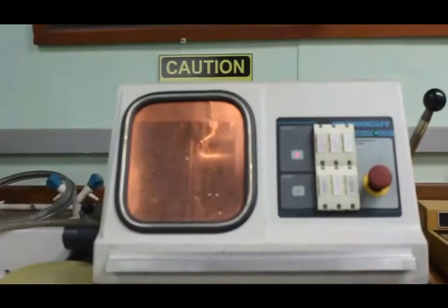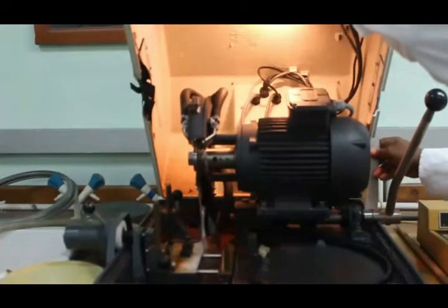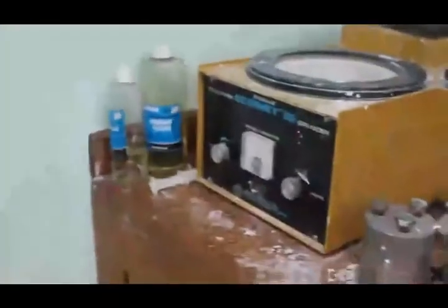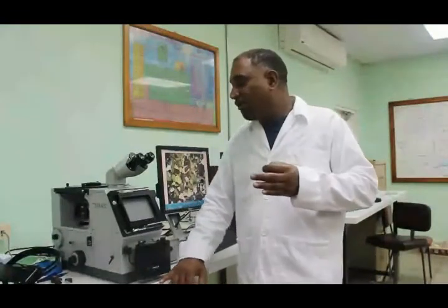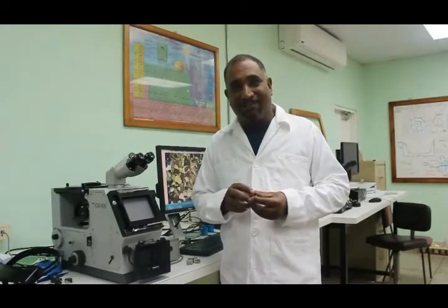We first start them off with sectioning, where we cut a small section of the sample, we take it to the press where it is mounted, and then we go into grinding, polishing, and etching. After the sample is etched, we will now bring it to the microscope and have them do what we call image analysis.